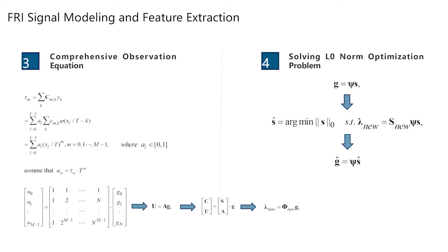In the ECT system, the number of pixels is much larger than the number of capacitance values obtained, which leads to the ill-posed problem of ECT image reconstruction and instability of the solution of the ECT inverse problem. It results in a low sampling rate, which ultimately reduces reconstruction accuracy. A new observation equation is constructed by zero vector filling and random recombination of row vectors.